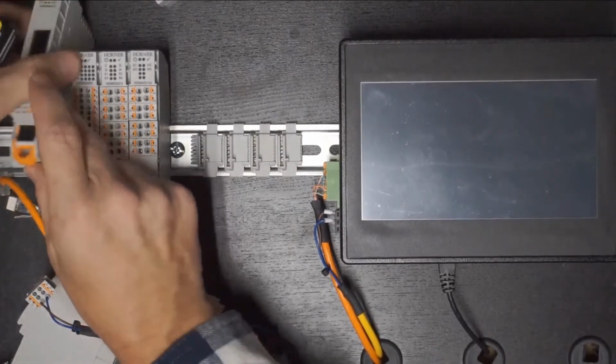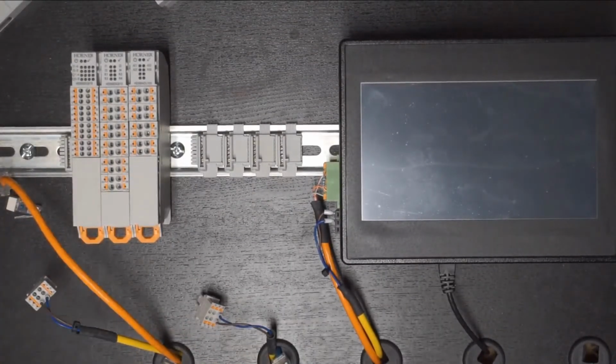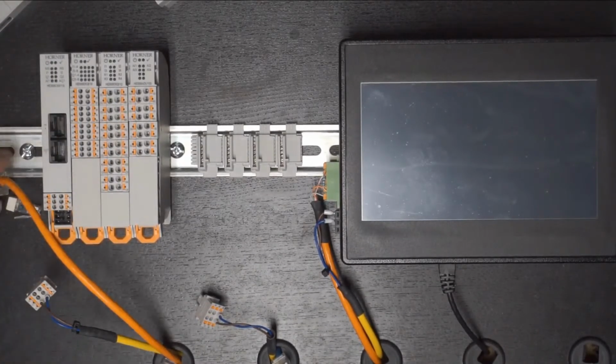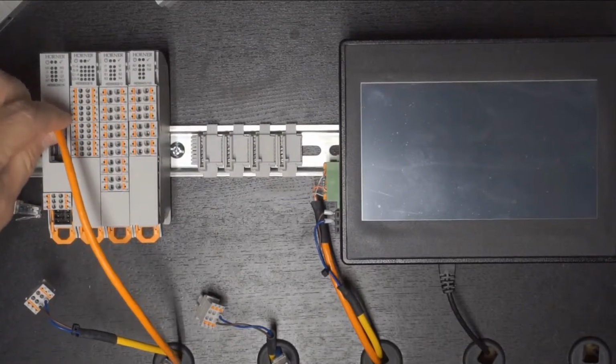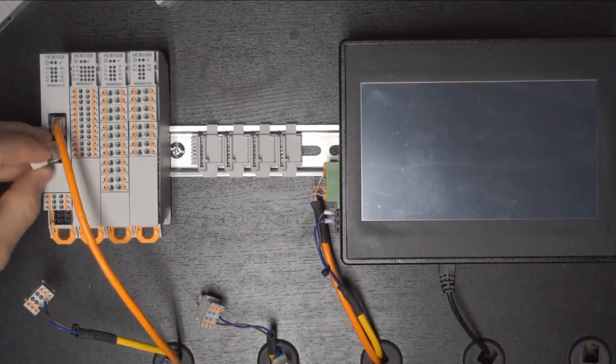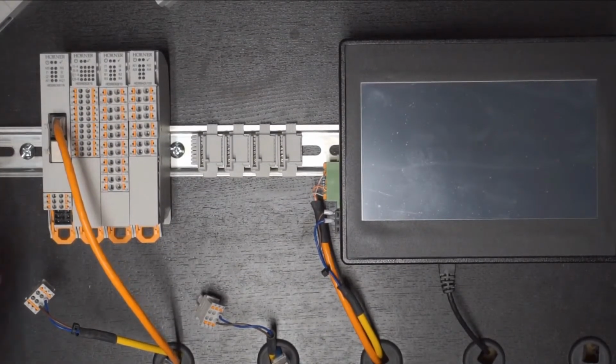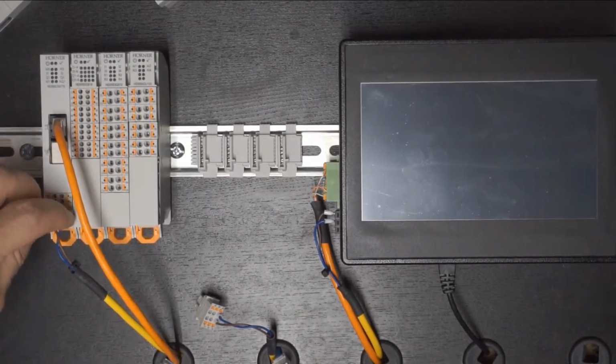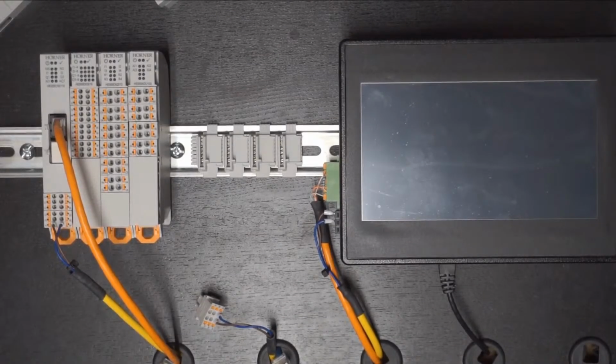Okay. And next thing I'm going to do is add in a new base. So this is my new replacement that I got from the factory. All right. So I'll reconnect my OCS cable and my terminating resistor. I'll reconnect my power cable to the new base. And let's go ahead and power up and see what happens.